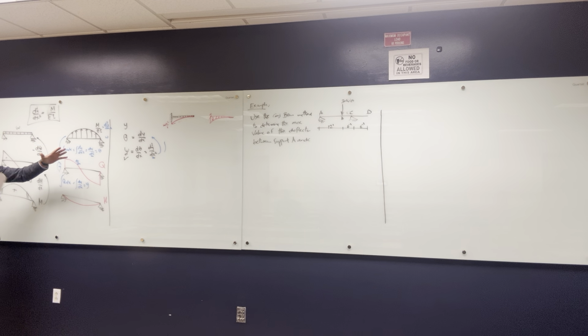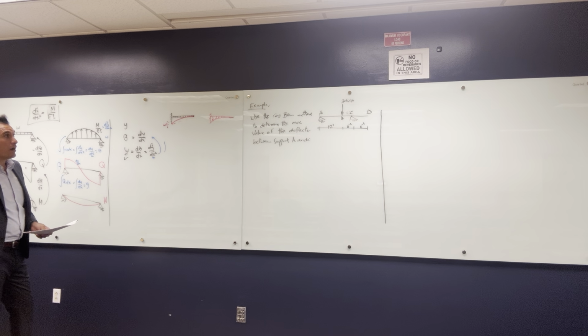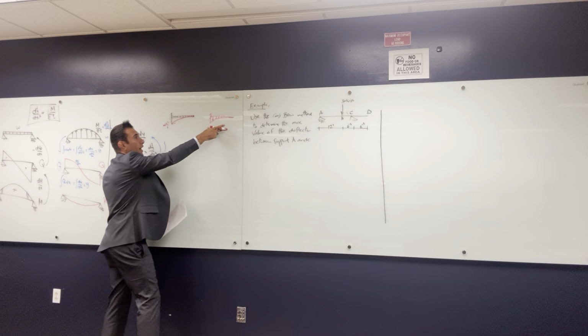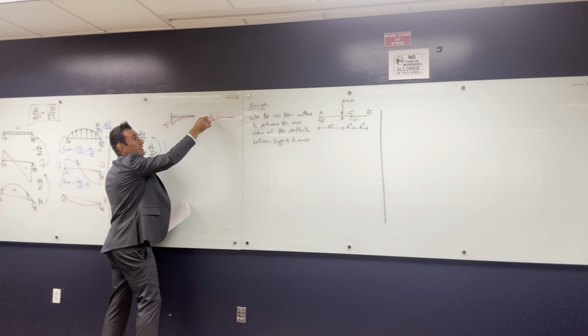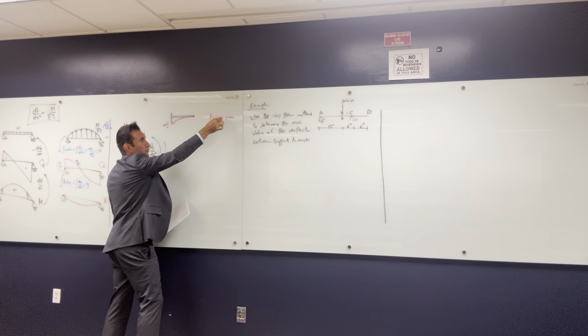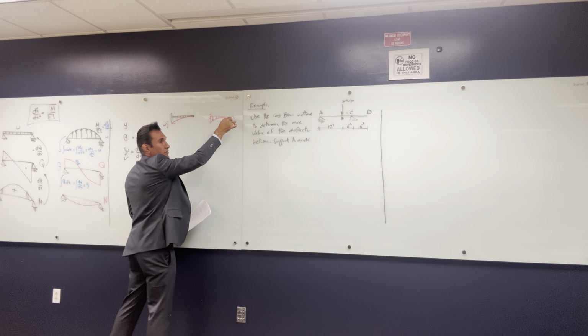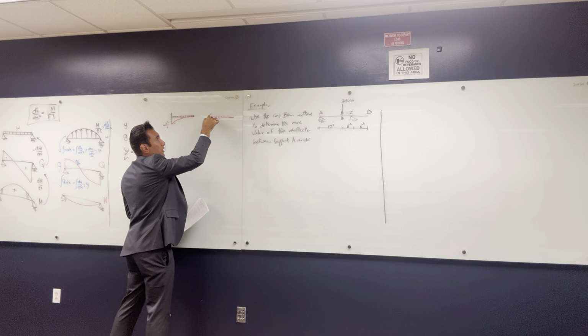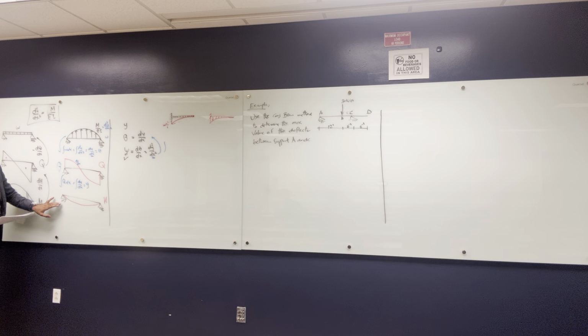We're going to make it a triangle minus a parabola, and I'm going to tell you how to deal with it. But if I did it that way, and I got the bending moment and the shear force diagram for this, I will find a shear here, right? And I will find a moment here. Once you draw the diagrams for this, you will find that the bending moment is 0 at the fixed end for this conjugate beam, and the shear force is 0, but there is a moment and shear at the free end. The moment means theta, and the shear means deflection.